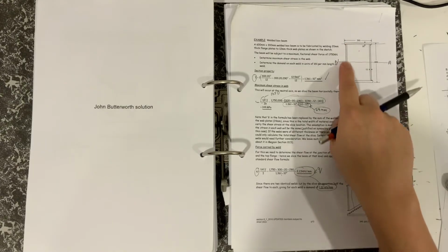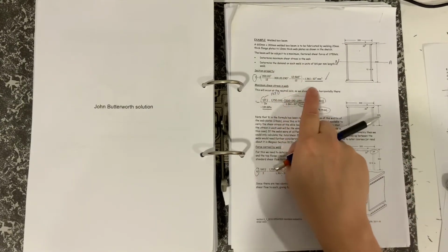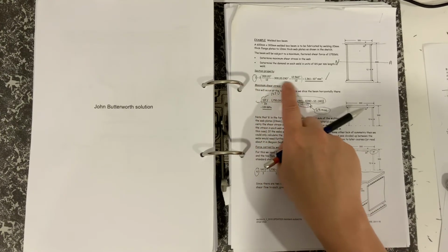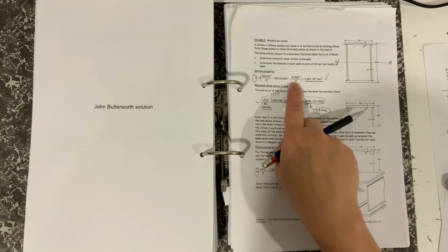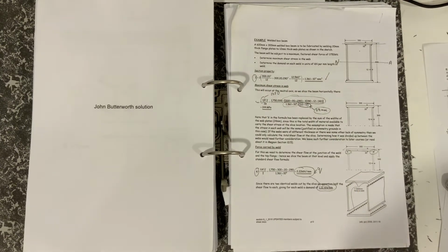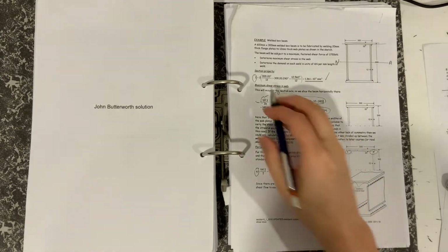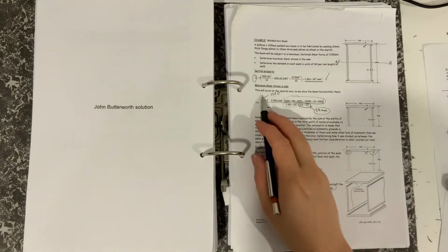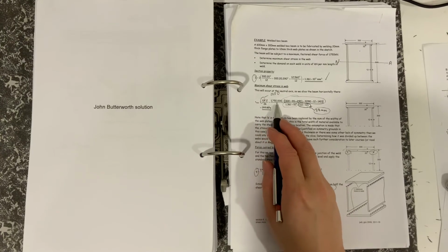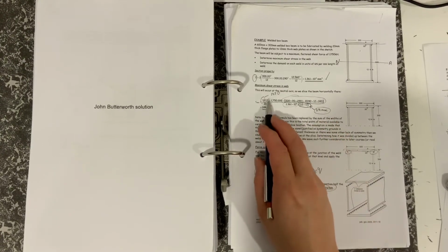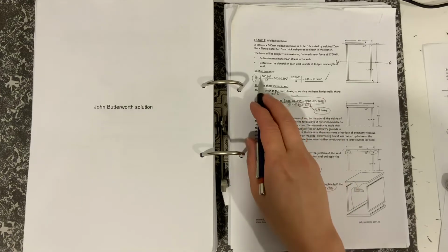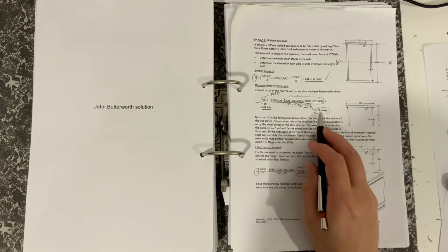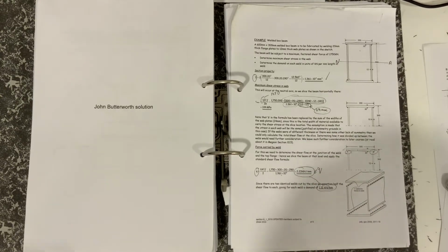The first thing to do is to work out the section properties, and you can see how everything's been calculated here. You can see that they've used the 24 because you can see the 12 and the 12 there. Divide by the I that you just calculated, and the b in this case is the 12 plus the 12, for the reasons I've just explained.